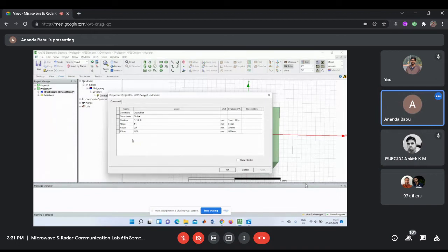That's why it is required to take the X value, Y value and Z value. So for the substrate, initially I'm taking -8.61, 7.39. So this is the X value position. This is the Y value. -8.61 is the X value, 7.39 is the Y value, 0 is the Z value.